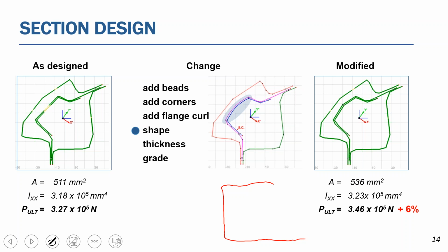It will calculate the warping constant for a section like this, which is very useful for twisting. If we calculate the effective properties, these very long, unsupported sections will probably cause a failure mode in the computation because they tend to buckle at extremely low loads.